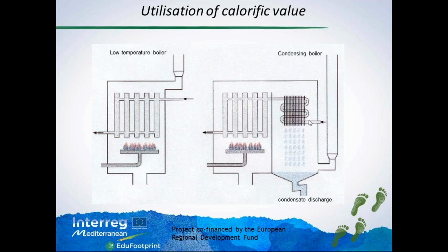So in this step, we have the possibility to use a quantity of energy that usually in a normal boiler cannot be used because it's present as latent heat. Only if the water coming in is colder than 60 degrees does this step occur, and it produces a lot of water, but it saves also a lot of energy. It's reused, and the temperature of the water here is higher than here, and higher than here.